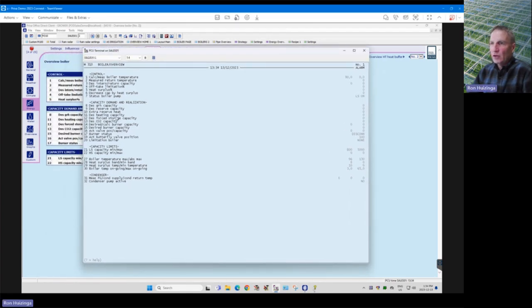So here we have a line called line 9, reserve capacity. The reserve capacity is basically the calculation of heat for that buffer tank. If you say I want 40% of heat in the buffer tank, and it drops below that, or it thinks, with the outside temperatures and the heat demand in the greenhouse, that it's going to drop below that, then it'll put a kilowatt here to run that boiler for reserve capacity.